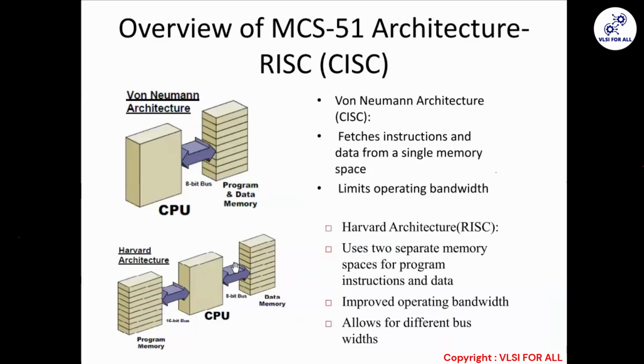Now, even before moving with this microcontroller, we must know two different architectures on which the microcontroller works. The first one is von Neumann architecture. And look at what this architecture is trying to tell. The CPU, the central processing unit, where the processing is happening, is dealing with program and data memory, and this program and data memory is in one stack, and a single bus is dealing with it.